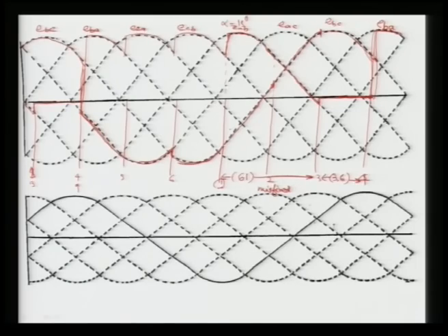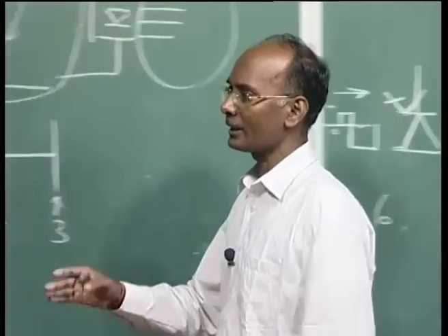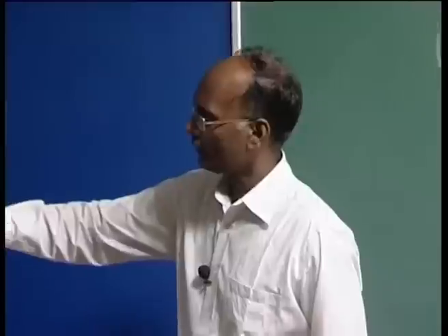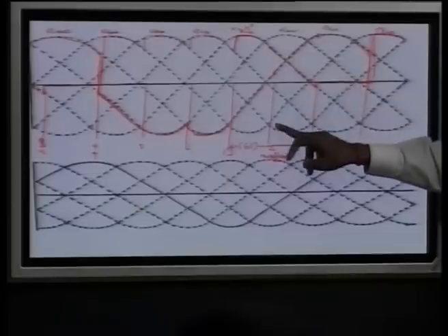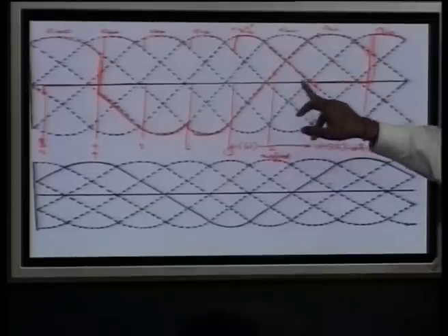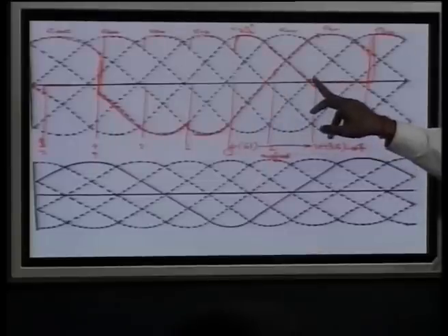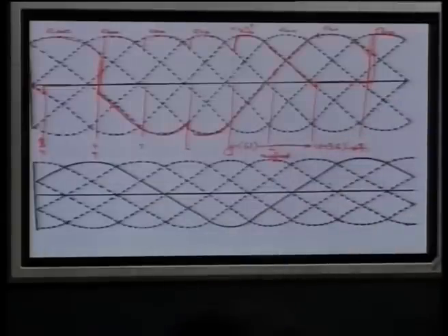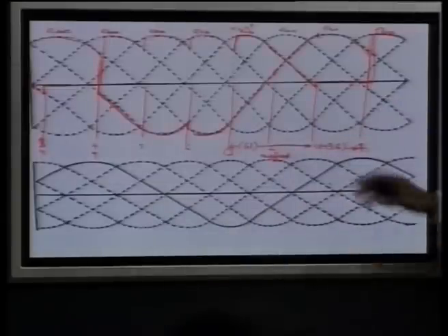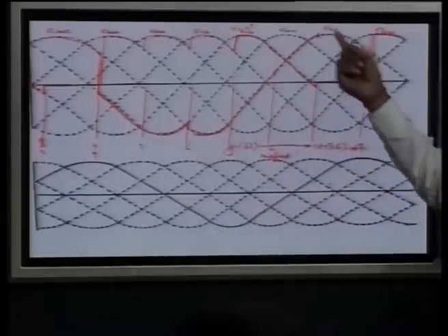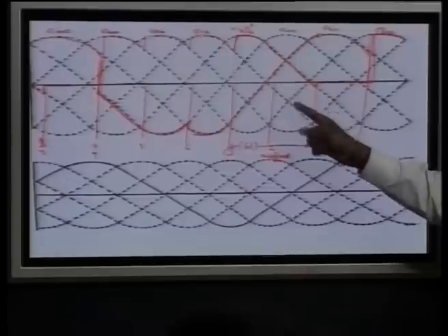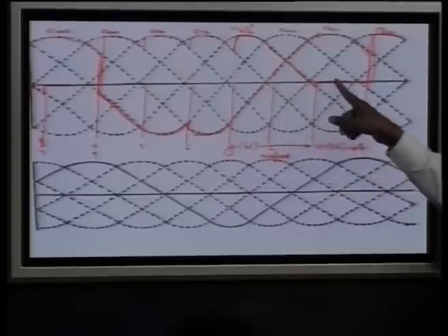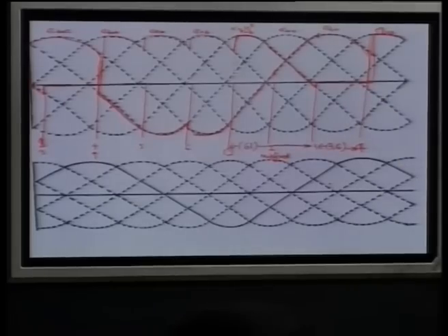So, basically this is the voltage, not that smooth, due to the different voltage appearing here. It was basically the conduction pattern here, but valve 2 is not conducting. So, in the whole cycle valve 2 is not conducting, so the voltage will not be 0, but most of the time the voltage is positive, and once it was conducting it will be 0 here. So, this is valve 2.